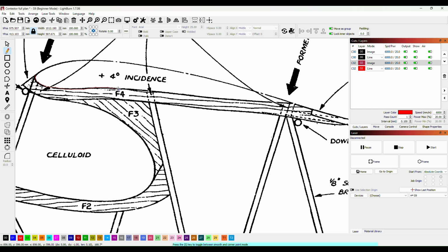Now what we'll find with this is that we need to smooth it out a lot later, but we can do that using our nodes again. And what we'll do is we'll convert each of them into a smooth curve node, and you'll find that that smooths out most of our little kinks and anomalies. Okay, and we're up to the top there, along, and then straight down to the end, and then just start the whole process again.